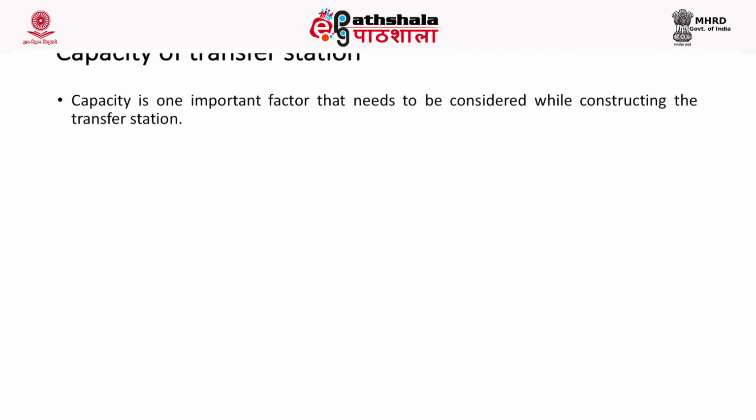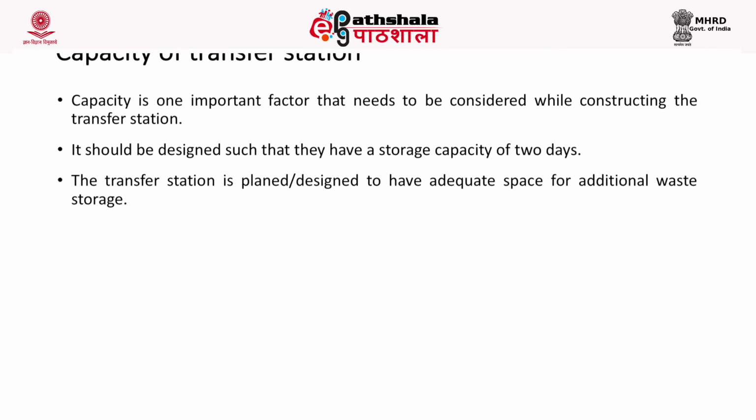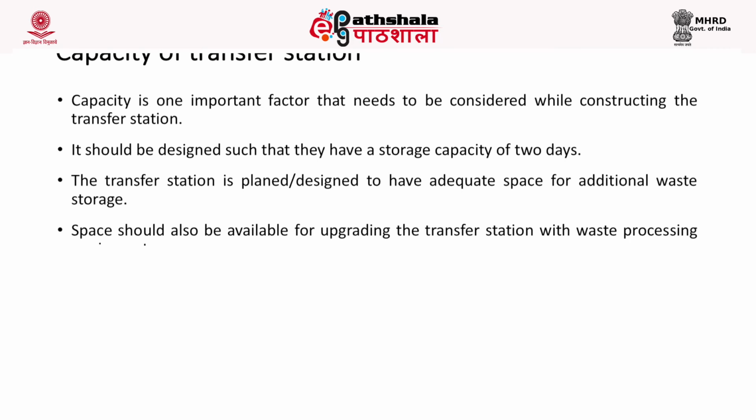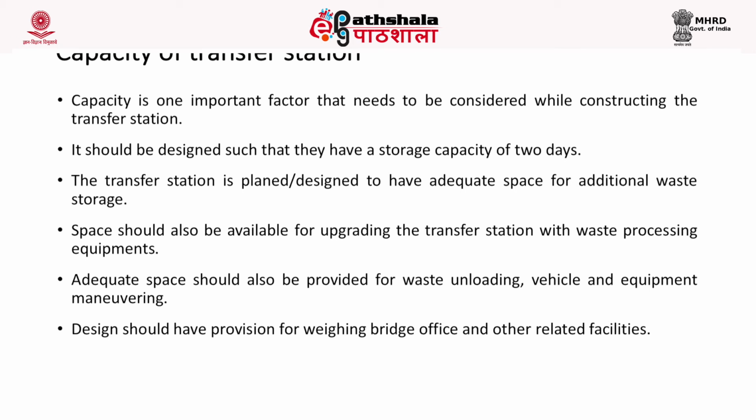Now, the capacity of the transfer station is another important factor that needs to be considered while constructing the transfer station. It should be designed in such a way that it has the capacity to hold or store the waste for 2 days. The transfer station is planned and designed to have adequate space for additional waste storage. Also, there should be space available for upgrading the transfer station with waste processing equipment. Also, there should be adequate space for waste loading, vehicle and equipment maneuvering. The design should have provisions for a weighing bridge, office and other related facilities.